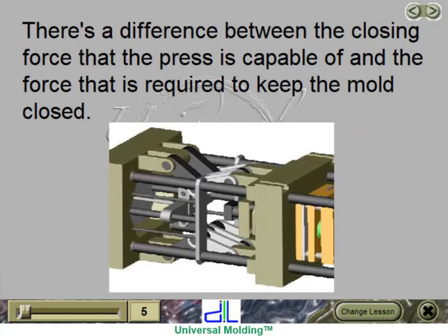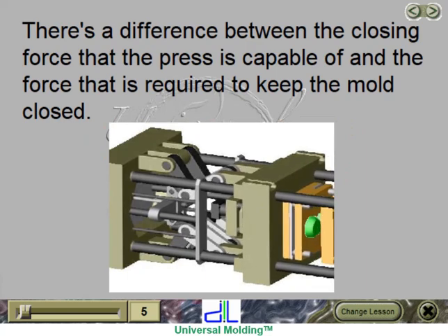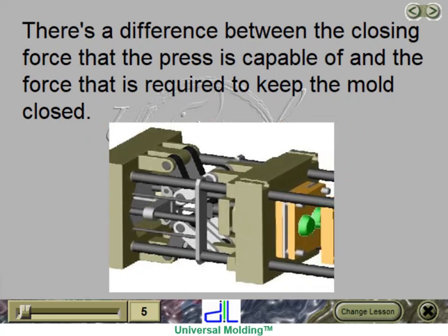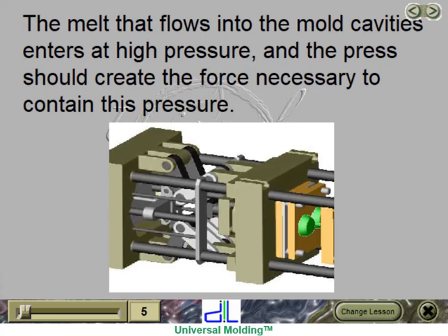There's a difference between the closing force that the press is capable of and the force that is required to keep the mold closed. The melt that flows into the mold cavities enters at high pressure, and the press should create the force necessary to contain this pressure.